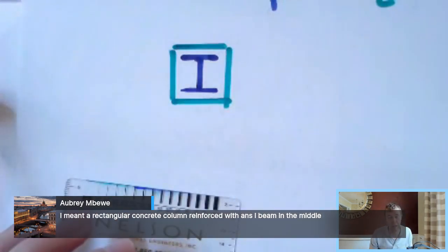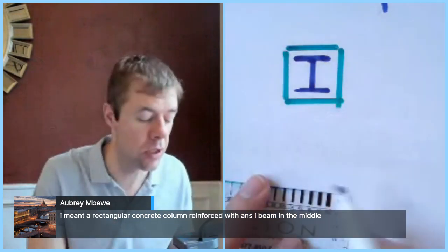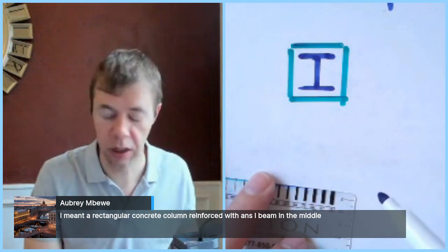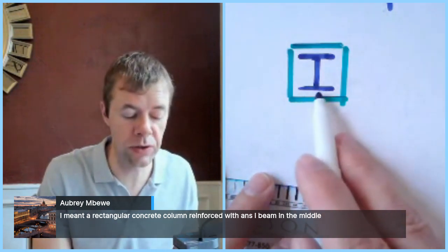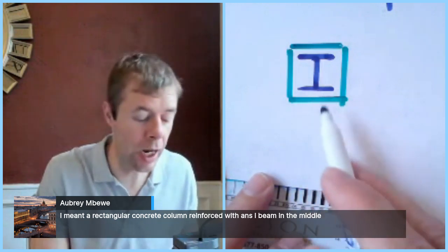And for those that are students at Oklahoma State University, if you go to Boone Pickens Stadium, which is our football stadium, hopefully we get back there eventually, and you look at the columns there, the large majority of the columns are this, where they did not have enough strength as steel columns. They actually put this concrete shell around the outside of it to increase the capacity of the structure. What it does is it makes it not buckle anymore. And the steel can help you on the inside. But in that case, not always.